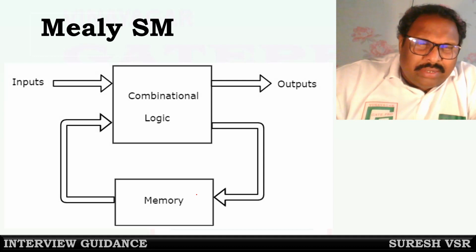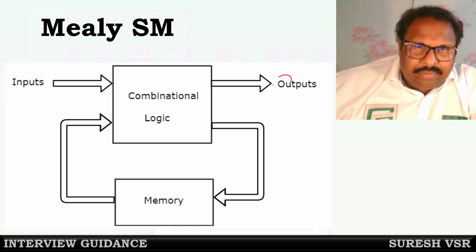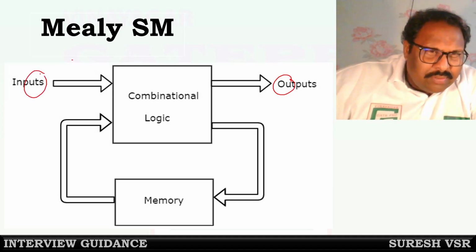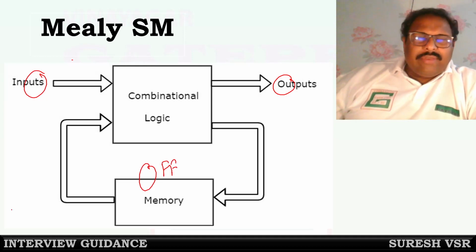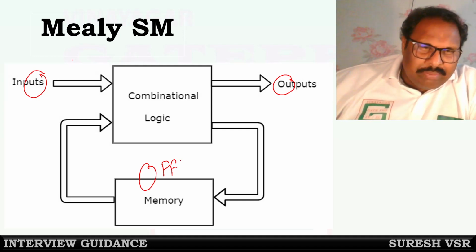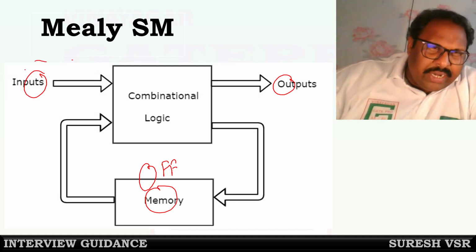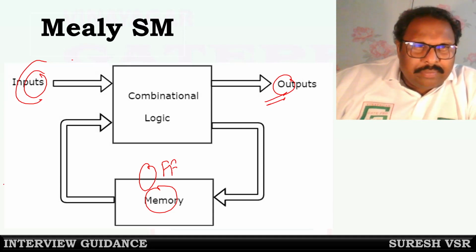Now, what is a Mealy state machine? In a Mealy machine, the present output depends on the present inputs as well as the states of the flip-flop. Even the previous states of the flip-flop also decide your present output. So there is a memory unit, with the previous states and present states, which together decide what output you get.